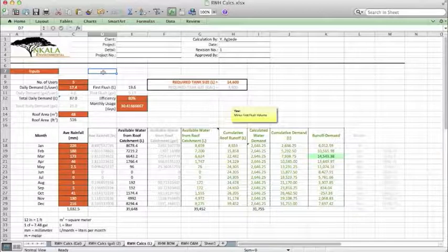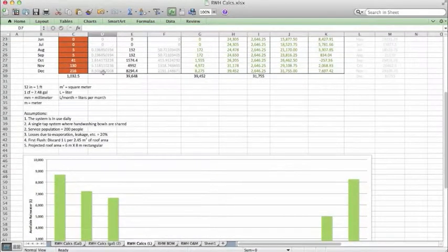All right, for our first flush, how do you design a first flush? Well, there's not a lot of hard science that goes into it, but just rules that have been observed through time. And the rule that we have for designing a first flush system is that your first flush should be able to contain the first gallon for every 100 square feet of roof area. And in liters, that translates to the first liter for every 2.45 square meters of roof area needing to be discarded.